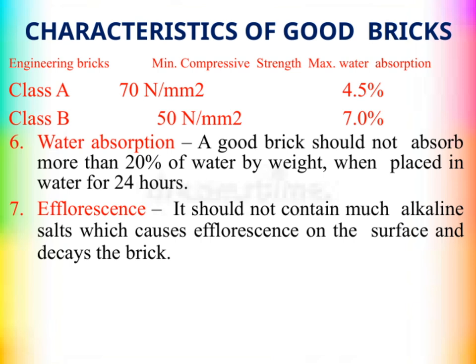Now, a key point to remember is water absorption. A good brick should not absorb more than 20% of its weight in water after being submerged for 24 hours. This indicates good porosity control and durability.